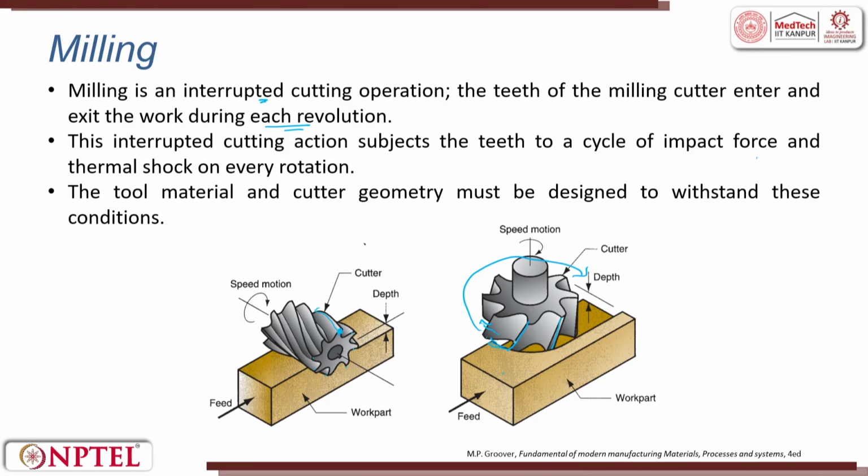The temperatures will be very high, but the teeth will also have time when they are on the idle cycle, where they will not come in contact with heat. So, they get cooled. Because of this action, you will not have tool wear as fast as compared to that of a single point cutting tool. The tool material and the geometry must be designed to withstand these conditions.